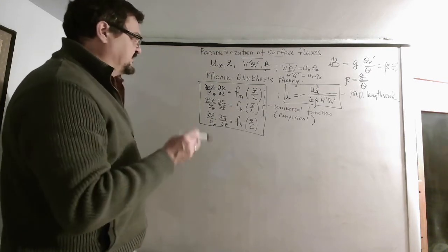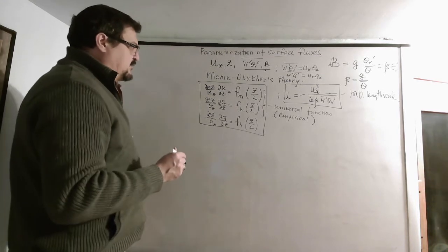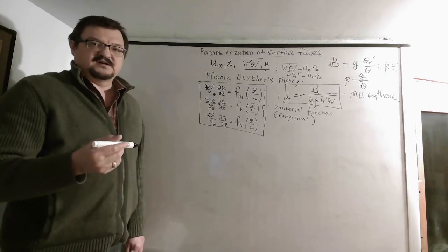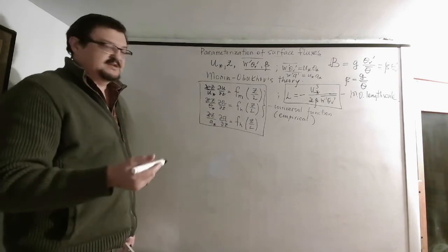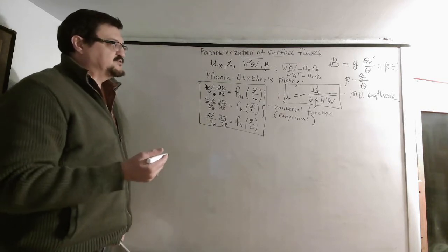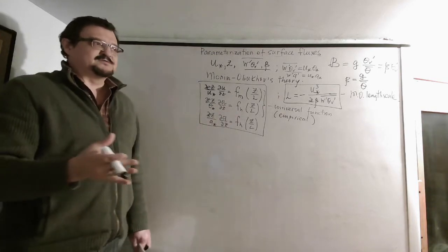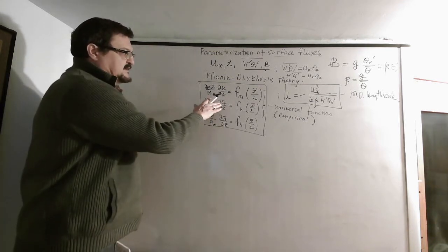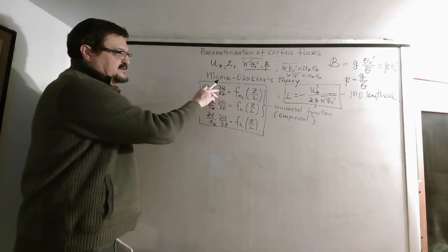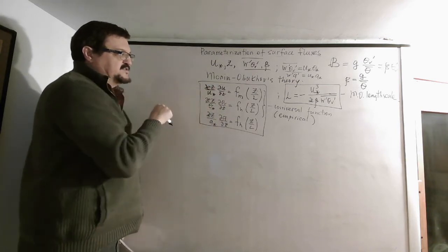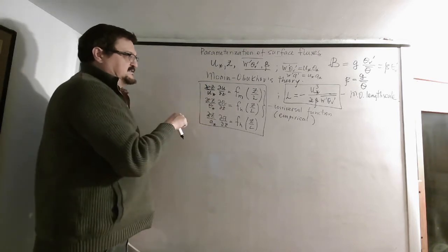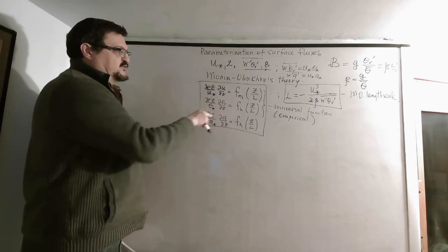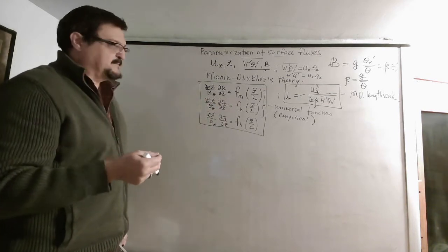So we assume they are integrated, and when we integrate, we then need to define roughness lengths. We have the same roughness length as before for momentum, but we also need roughness scales for temperature and water vapor. For momentum it's the height where velocity becomes zero, but for temperature and water vapor it's the height where these values become equal to the surface value.